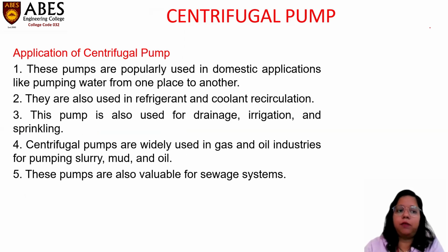Now, where these centrifugal pumps can be used? These pumps are popularly used in domestic applications like pumping water from one place to another. They are also used in refrigerant and cooling recirculation. This pump is also used for drainage, irrigation, sprinkling. These are also used in gas and oil industries like pumping for slurry, mud and oil. They are valuable for sewage systems also.